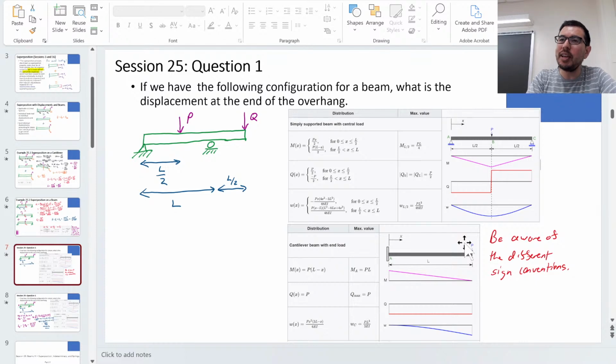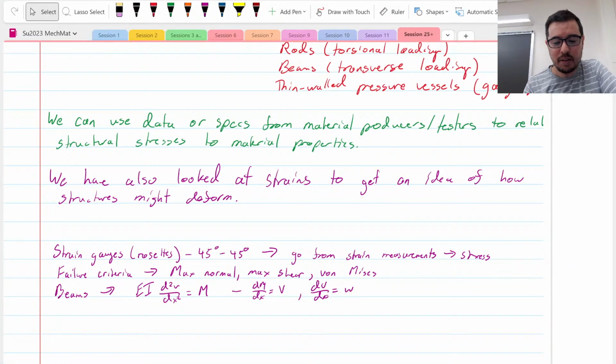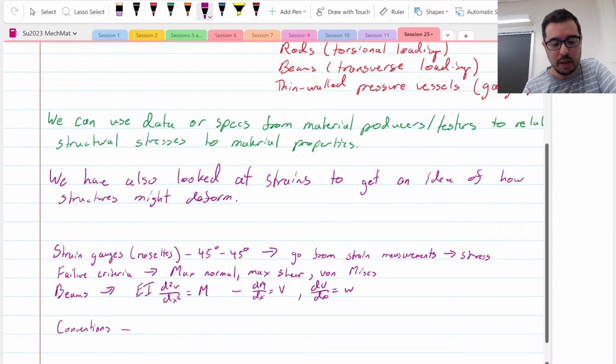Gravity works downward, so I can completely see why people would ask, doesn't it just make more sense to write V positive going downward? That's not what Hibbler has done, all right? And we've developed a whole set of conventions, and I don't want to mess up one. If I just change one, then I have to start flipping arrows on other conventions. But yes, this is a convention: V of x is greater than 0 when deflection is upward.